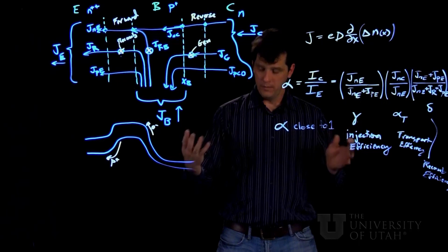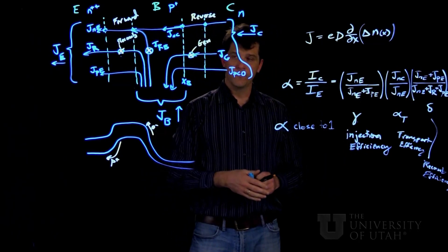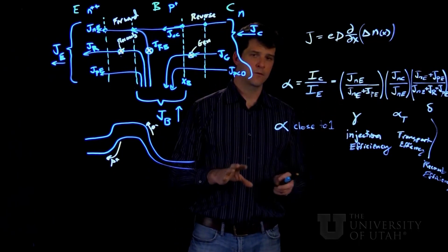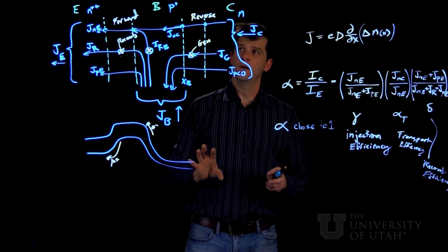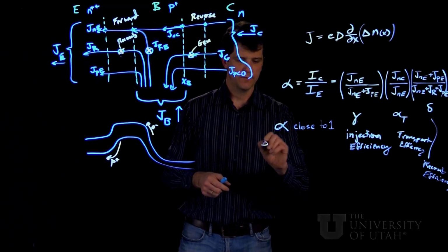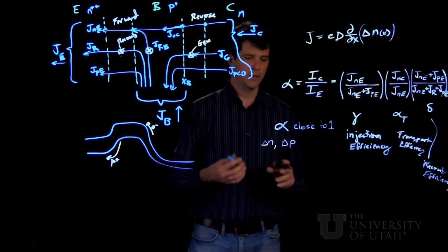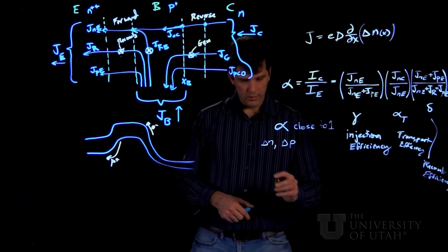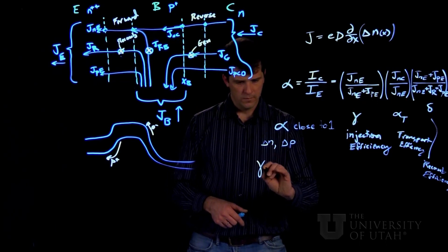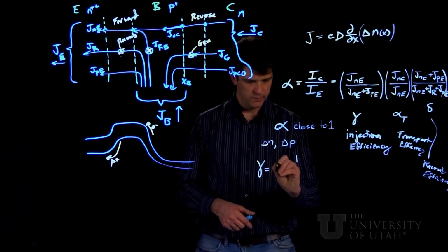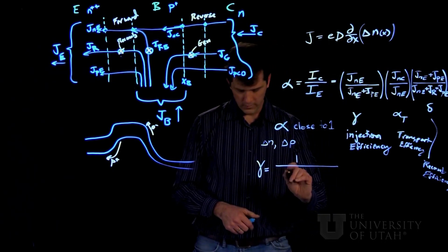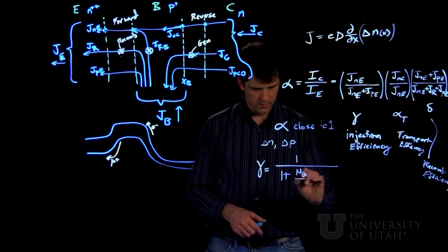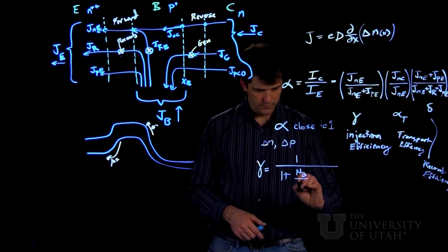Okay, so the last exercise we can do is to summarize these three factors from all of the expressions for the delta N's and delta P's that we got. And I'm not going to derive it, it's derived out in the book. But what we can see is each of these efficiencies can be reduced to a simple expression that involves only the parameters like doping and diffusion lengths.